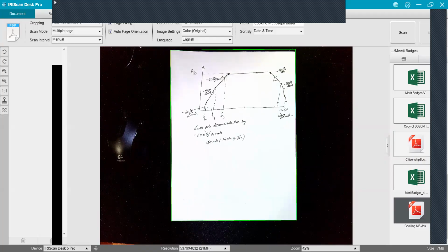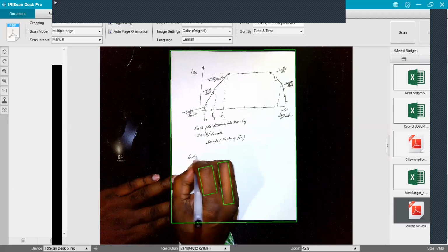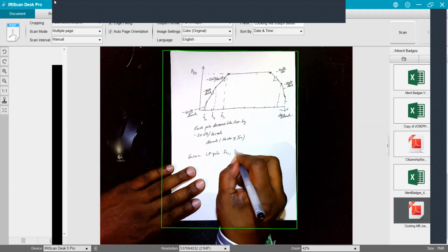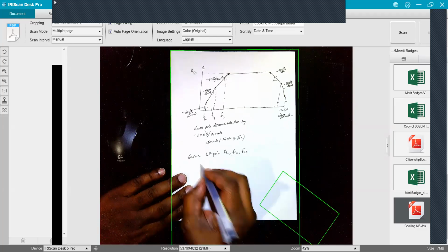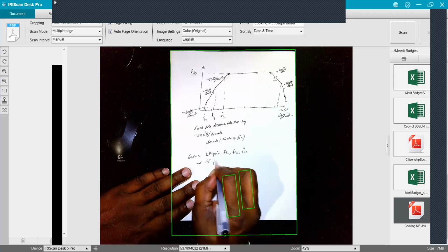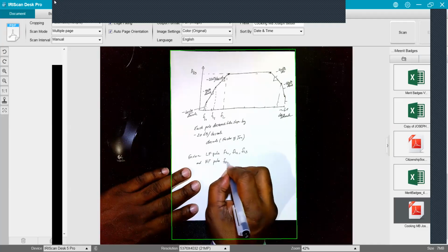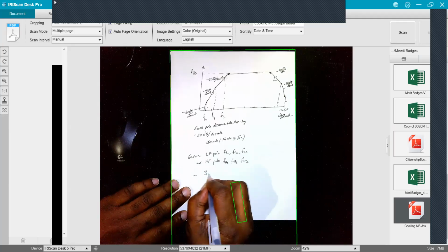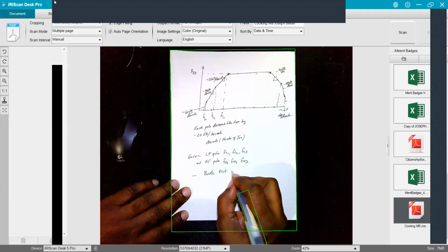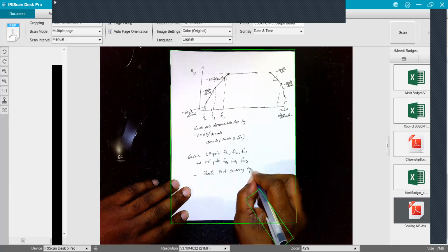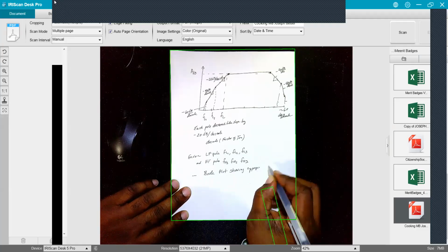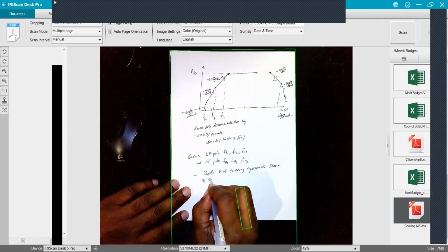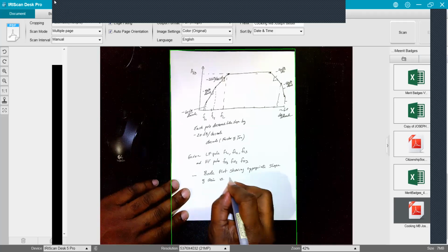So if you're given say low frequency poles FL1, FL2, FL3, and high frequency poles FH1, FH2, and FH3, you should be able to do the voltage plot showing the appropriate slope of the gain versus frequency.